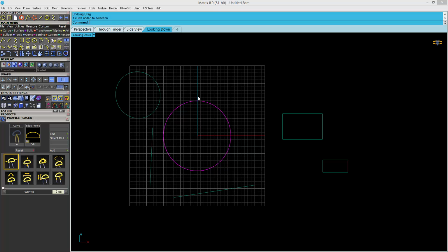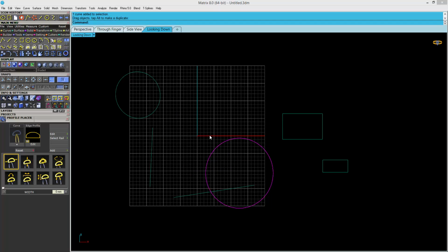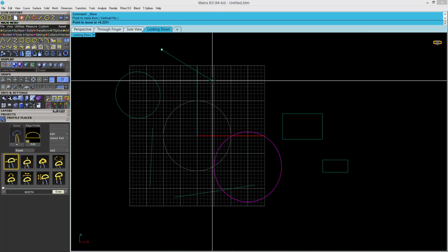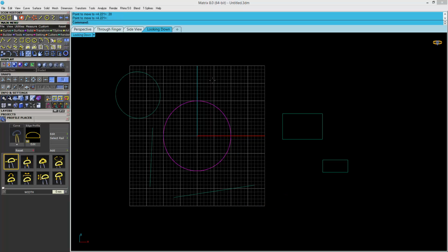I avoid clicking on it and then dragging like this. Never ever do this. Just select this. If you need to move, select, click here, and then just type in a value like 20 millimeter, 10 millimeter, 5 millimeter, and then press left click. It will do its job. But don't do the dragging stuff.